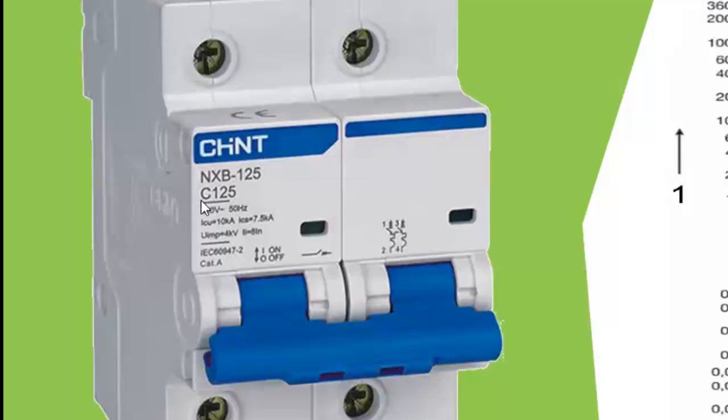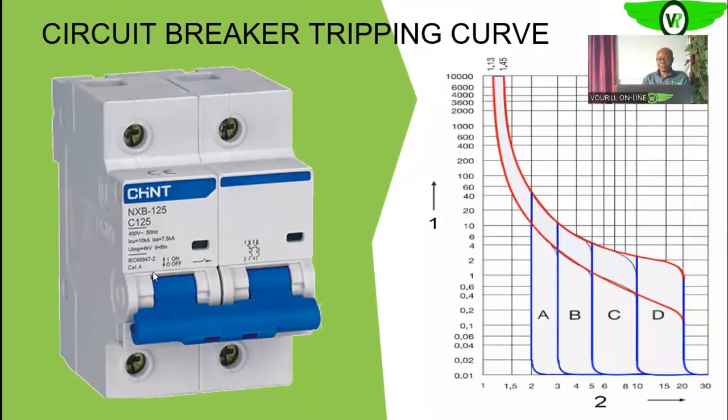So here it is a C curve, which is this particular curve. It means that this breaker will trip instantaneously when it sees something between 5 times and 10 times this 125 amps.